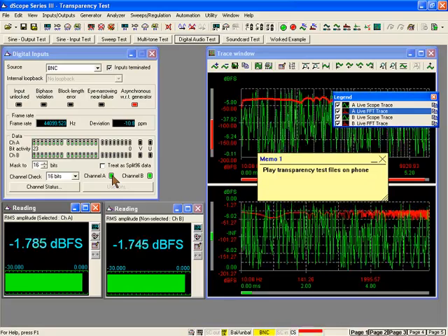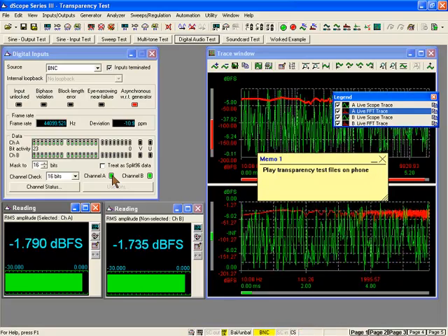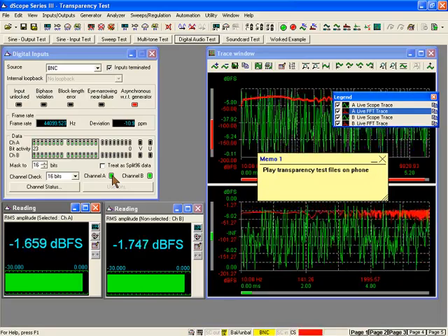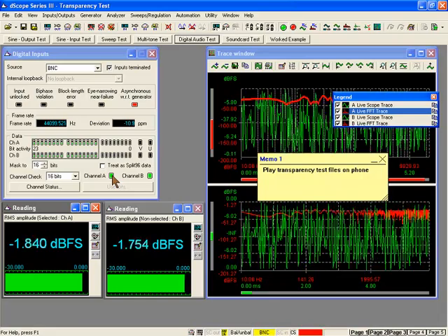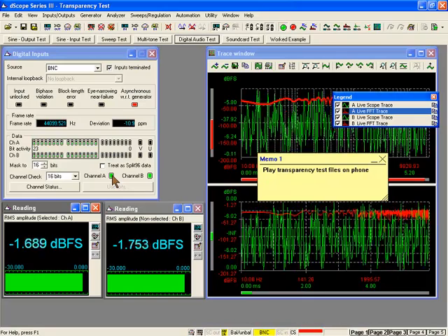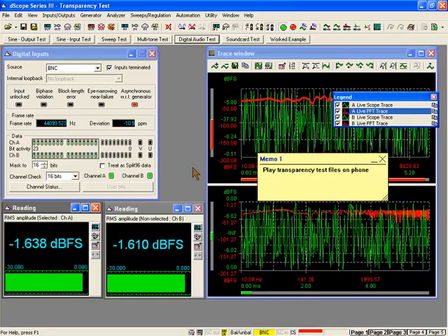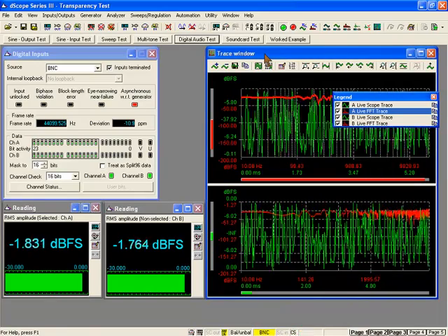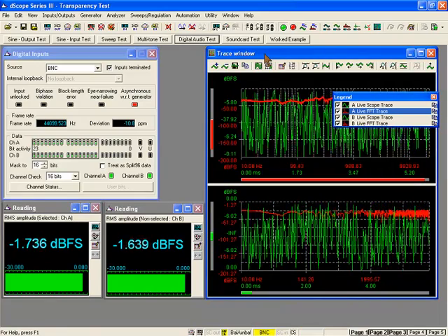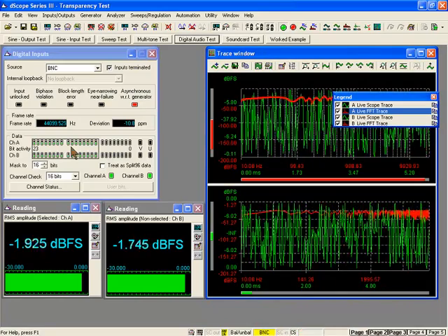So that's the monitor outputs from the Dscope Series 3 test system, and we're listening to a pseudo-random sequence which statistically is very close to white noise, and it sounds like white noise. So this is a very good test for looking into potential bit errors in your playback audio device. And right now everything's perfectly fine.